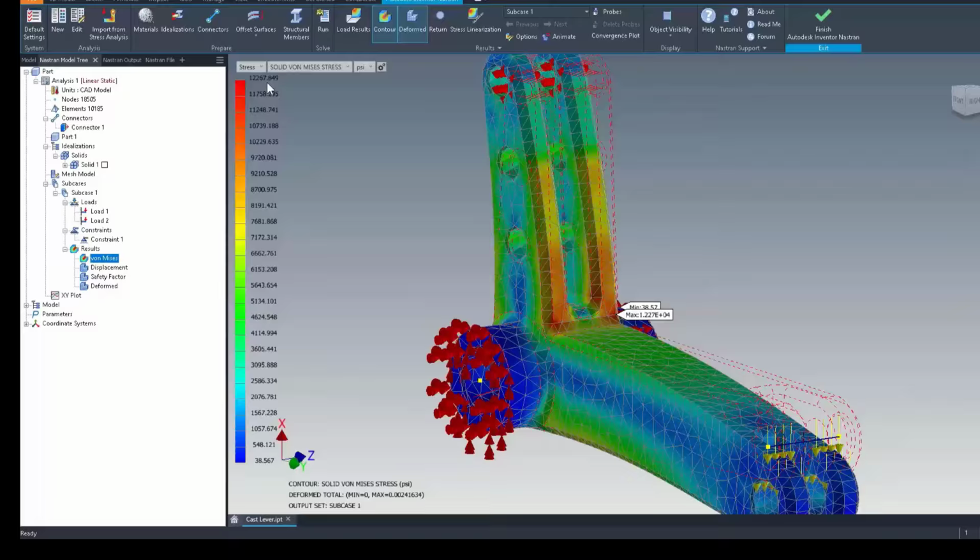Once you get 10% or less, you're pretty well confident that, hey, we've got a good mesh, we've got good properties, we've got good setup, things aren't getting really whacked out of control here. So this is probably where we're seeing the stress. This is probably the amount we're seeing within a certain level of confidence. And some corporations even say, let's go finer and do a 5% change. But kind of the ballpark that everybody at least shoots for is a 10% change. Once you get to that 10% or less, you've got convergence of the results.